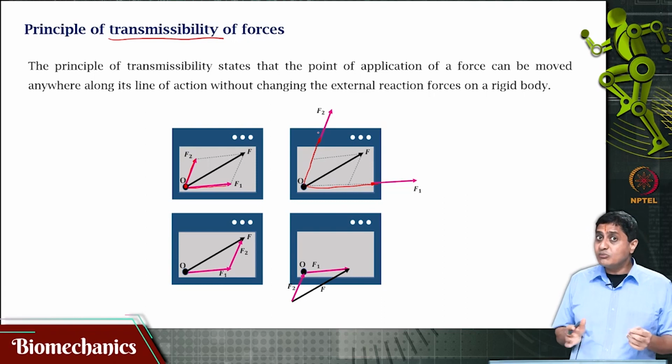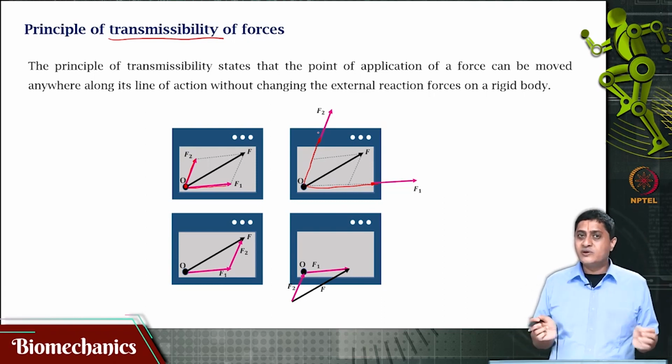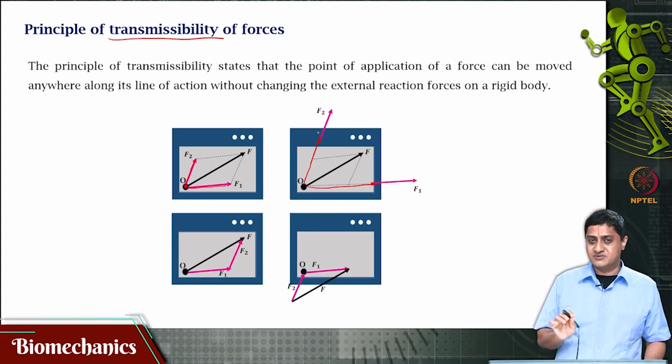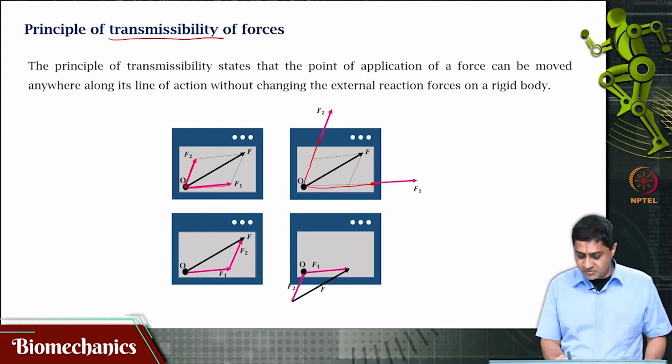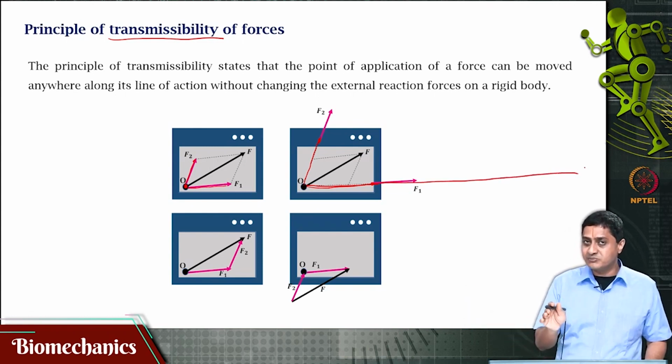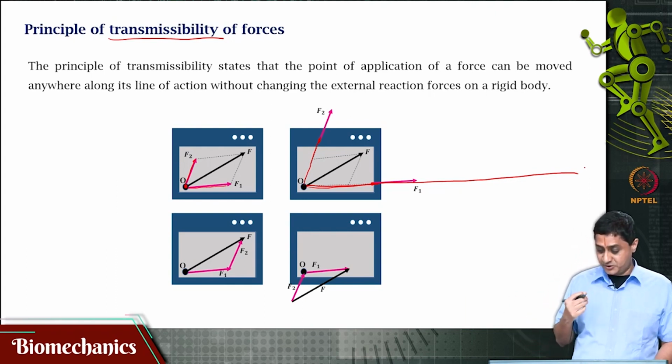Important: you cannot move it anywhere you want. You can only move it along the line of action of that force. So for F1 it can only be moved along this line, infinitely anywhere, but I cannot move it to any other point. Okay, important to remember that.